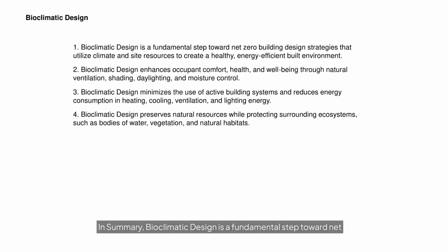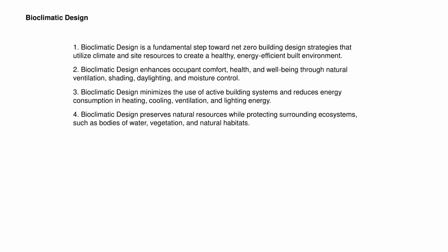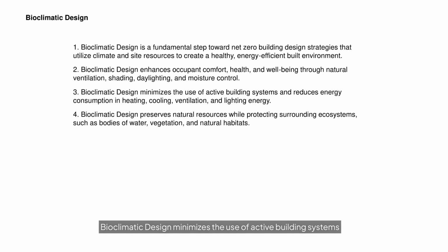In summary, bioclimatic design is a fundamental step toward net zero building design strategies that utilize climate and site resources to create a healthy, energy-efficient built environment. Bioclimatic design enhances occupant comfort, health, and well-being through natural ventilation, shading, daylighting, and moisture control. It minimizes the use of active building systems and reduces energy consumption in heating, cooling, ventilation, and lighting. It also preserves natural resources while protecting surrounding ecosystems, such as bodies of water, vegetation, and natural habitats.